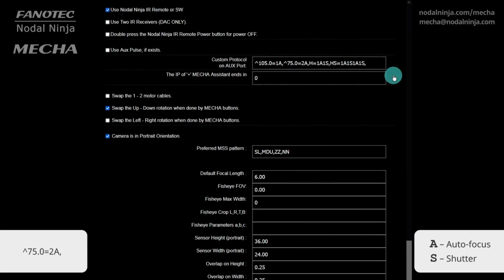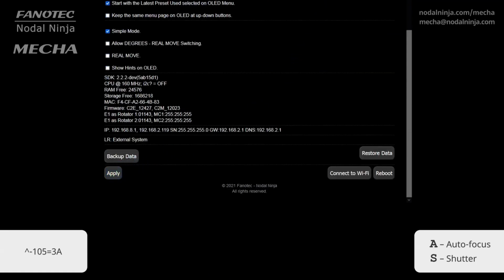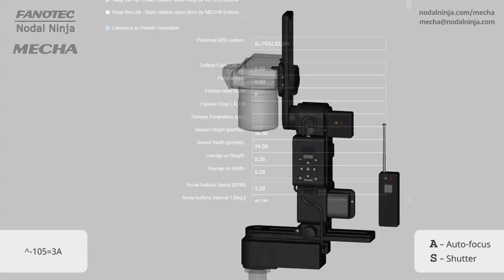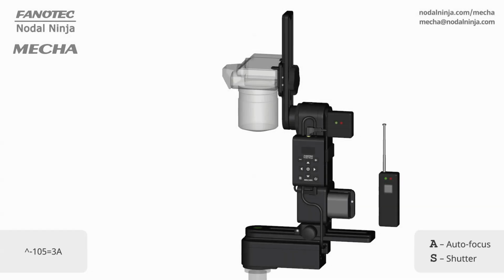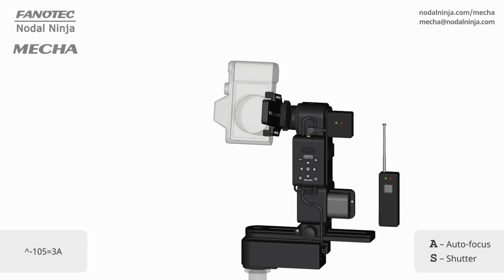With this new command, the upper rail can be rotated 105 degrees downward from its current position when the release button is half pressed 3 times. A full press of the release button rotates the upper rail to the home position. You'll remember we set a new home position at 15 degrees above level. With 3 half presses of the button, the upper rail rotates into the parked position.